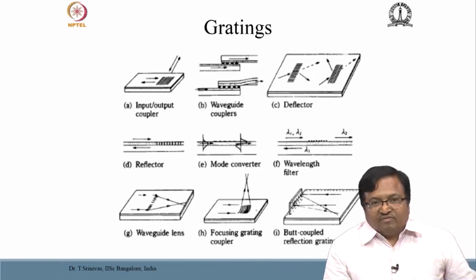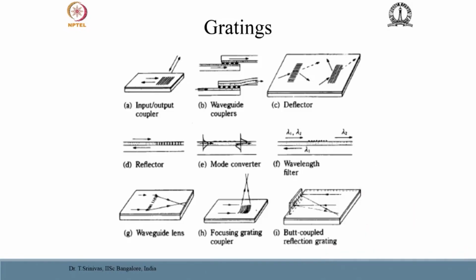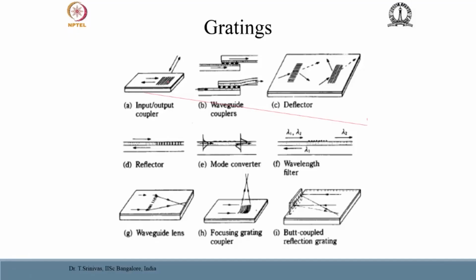Gratings have many functions in many applications in optics and integrated optics. I am showing you some applications. The gratings can be used as an input output coupler. This is one of the important applications at present. One of the important problems I can mention in integrated optics is coupling light from input optical fibers onto the chip, and gratings do a very good job in this connection.